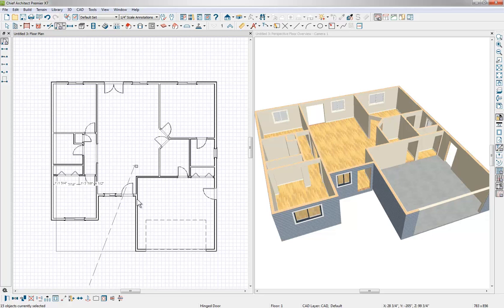So that's the idea. I'm not going to go through creating all these layers. I just wanted to get across the point that we can go in and create layers for existing doors, windows, walls, roof, foundation, and assign those to existing status, and then mark that they're not included in the material list. And that's a way for you to very finely control your material list.